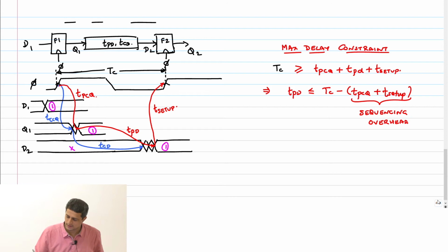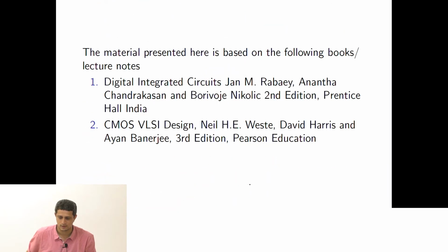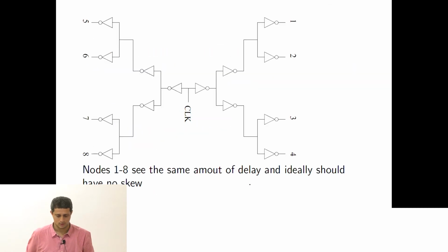So now, maybe I should just discuss that right away. These two clocks to F1 and F2 are coming from different points on the clock distribution network. So how does clock distribution happen? Let me show you that very briefly here. The clock generation happens at a central point in the chip, because the clock has to be insensitive to temperature and voltage changes.